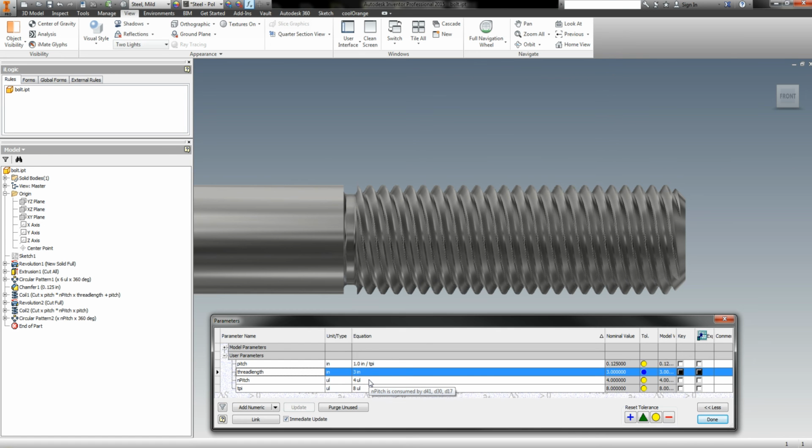Okay. I've also seen this come up in the Inventor General forums, talking about 3D printing these threads as part of the incentive for modeling them. Otherwise, you would just use the cosmetic threads that Inventor provides, because it makes your models run faster to use that rather than model the threads.